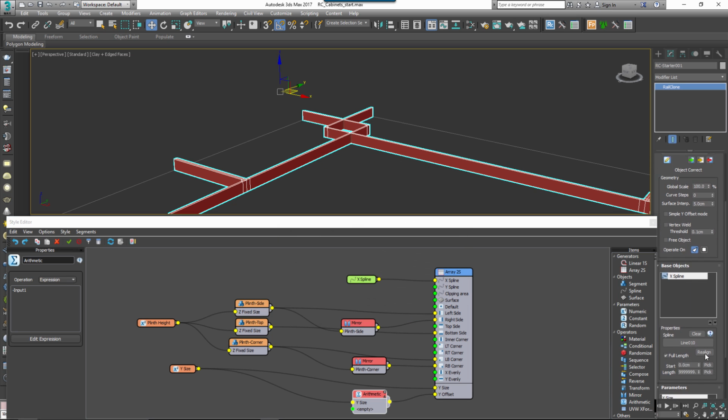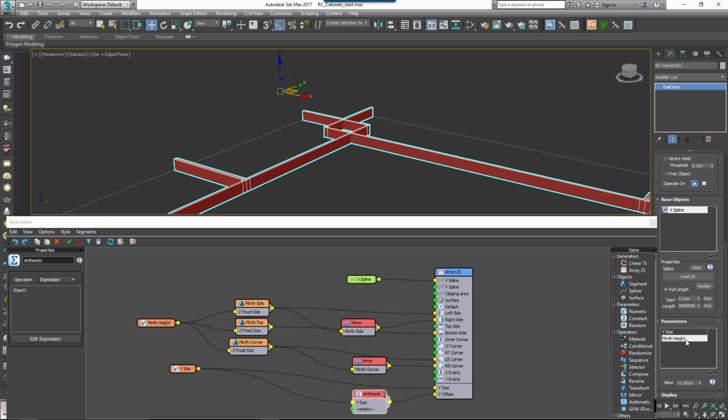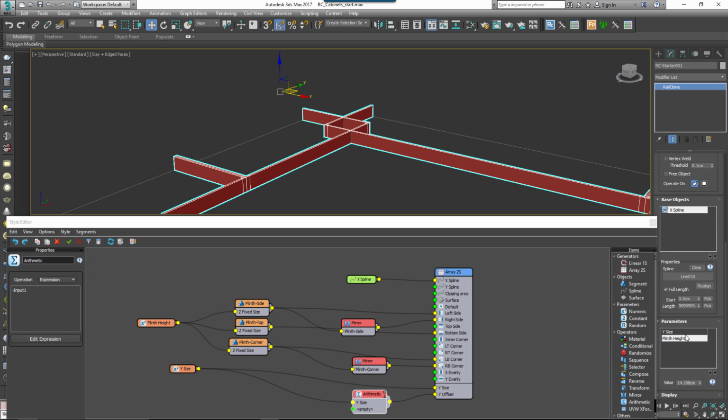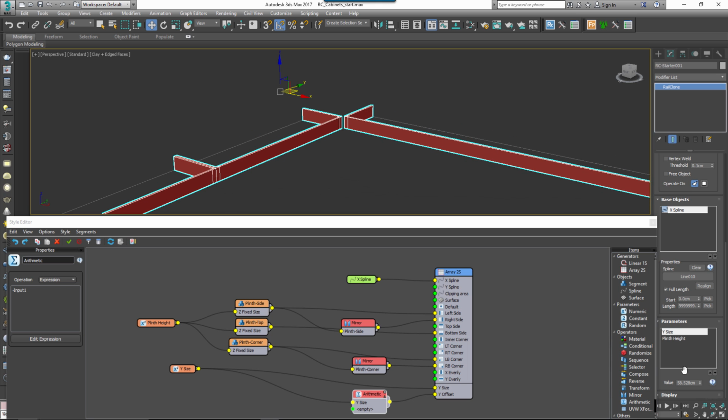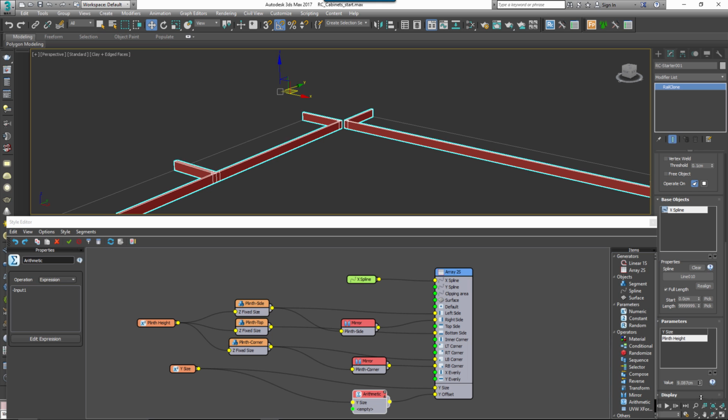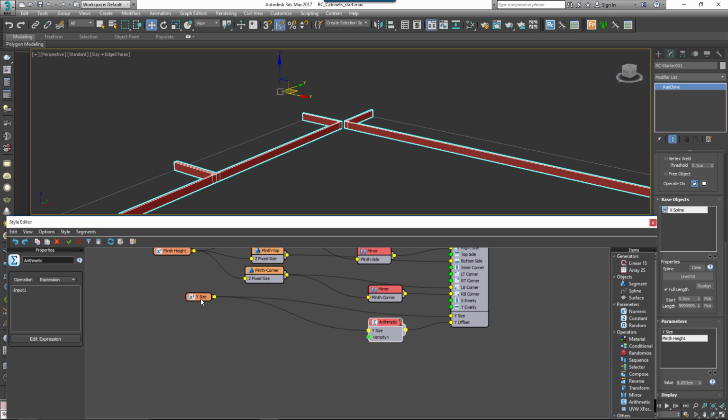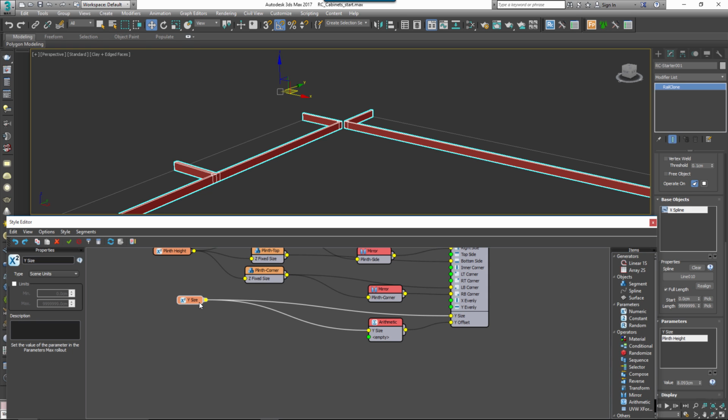Once you've done this, you can now adjust the depth of the plinth from the modify panel, and the back of the plinth will always be aligned with the spline. To make the style even a little more flexible, we also want the ability to offset the plinth so that it's stepped in from the cupboard front. In this setup, the Y size will set the cabinet depth and then we'll deduct from this a plinth offset.